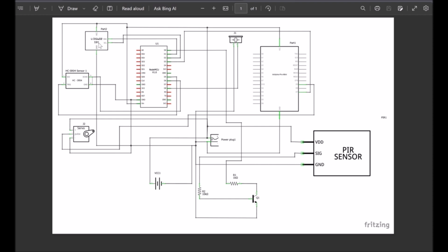We use the passive infrared PIR sensor to detect when a person is near the trash bin and wants to make use of it. The PIR motion sensor would be placed in the design at an angle where the viewpoint will be limited to only people in close proximity. This choice is as a result of the absence of a sharp fisheye infrared sensor. We used an NPN transistor to drive the piezo speaker to beep anytime we needed to alert the user that the trash bin is full.